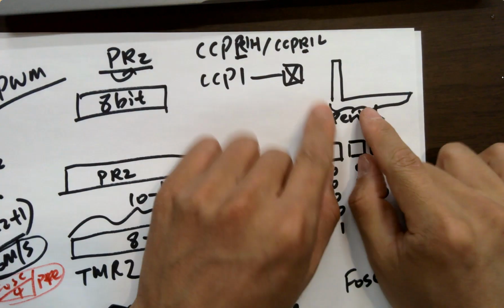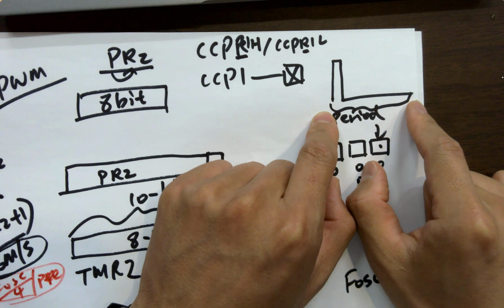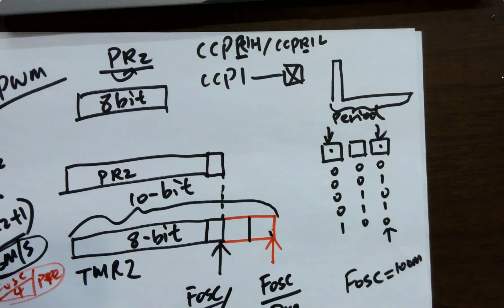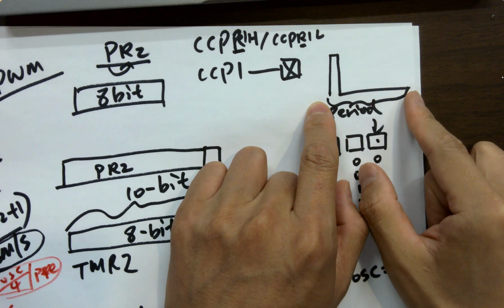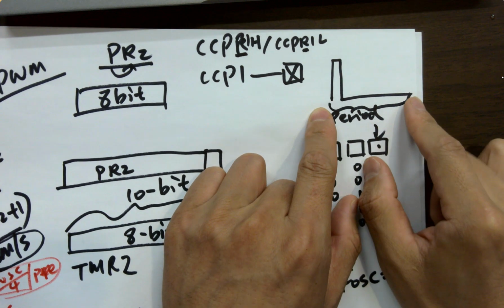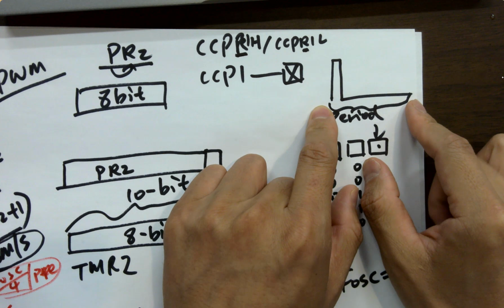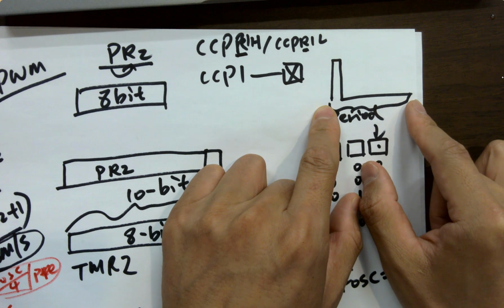So why do we need that? Why do we use PWM? You know it's useful, right? You can turn on an LED, dim it, make different brightness. You can also use this pulse to control what? Motors, DC motors, right? Same concept. You can control the speed, the DC voltage, very accurately, actually, and give a feedback.